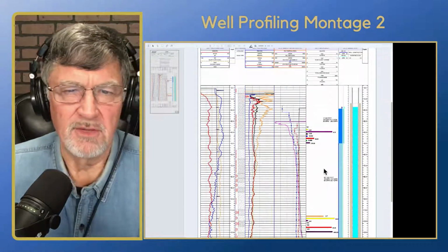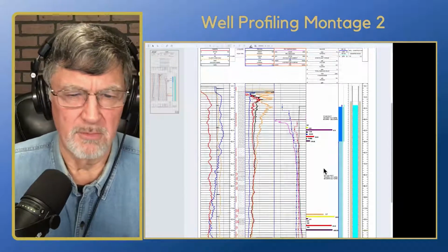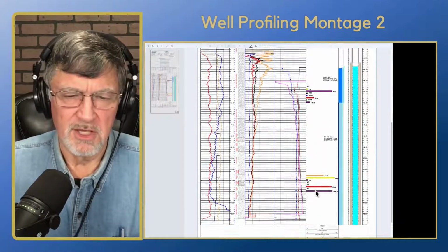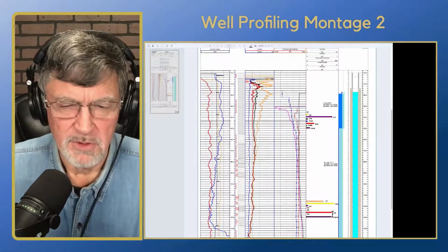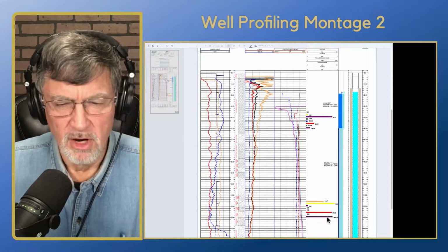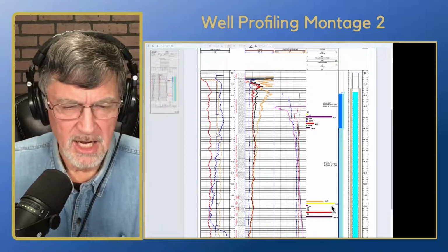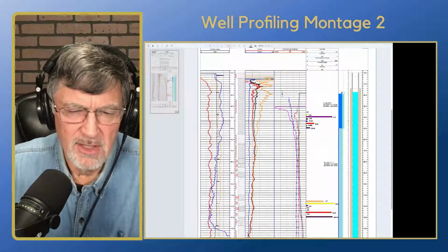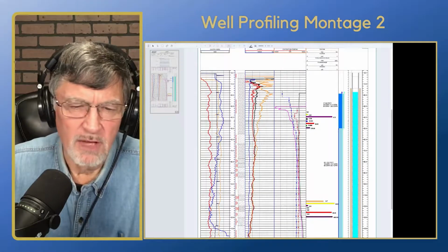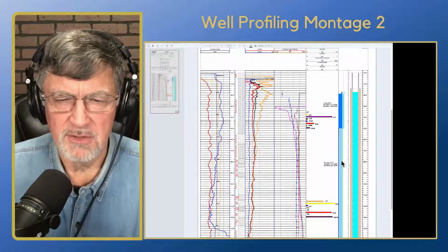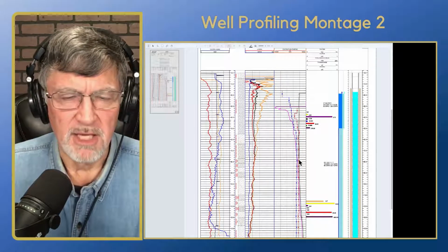The legend is a little bit hard for me to read right here, but you can see we did some specific interval testing here. We did a couple zones here. You can see markedly different water quality down below. Our TDS was way high, and our flow is actually down. Not a whole lot of flow down there, so we decided to screen that zone off and actually construct the well from 80 feet up.